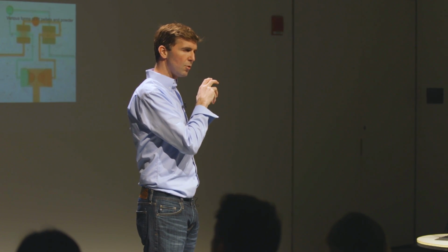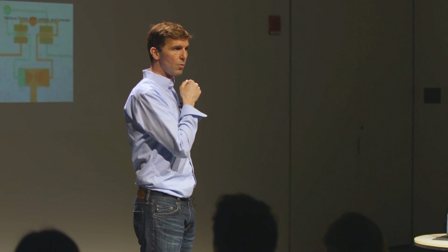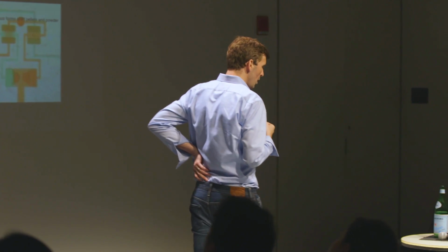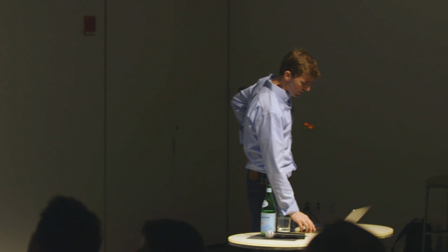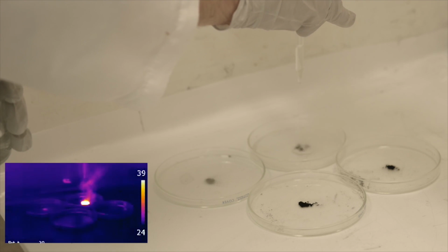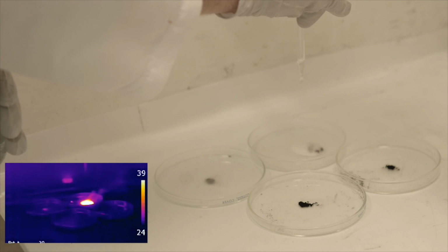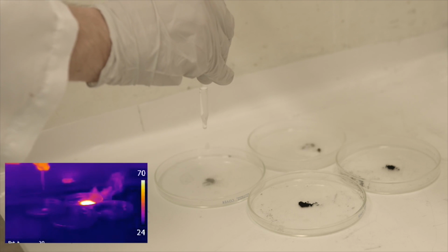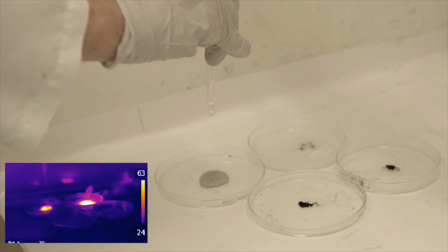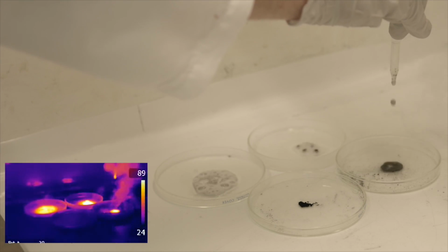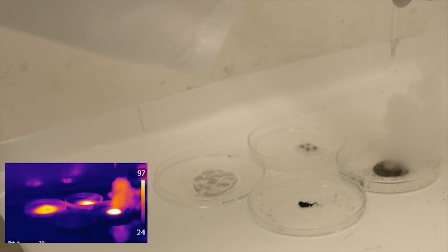But how do we think about creating a little controller that's soft? How do we think about having power that's soft? Certainly not traditional batteries. Long story short, we leveraged chemical power for these systems. The fluidic-based actuators require pressurized fluid, gas or liquid. So we rely on peroxide decomposition, monopropellant decomposition, in this case hydrogen peroxide, in the presence of a platinum catalyst. It's a very energetic reaction, and I can tell you about the kinetics of this later, but the products are hot gases that are useful to power whatever fluidic actuator you want downstream.